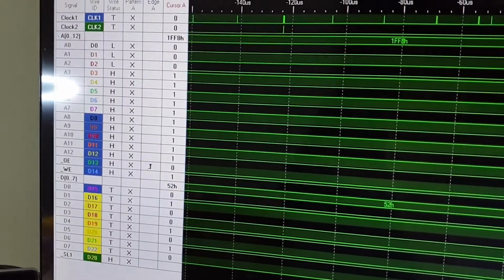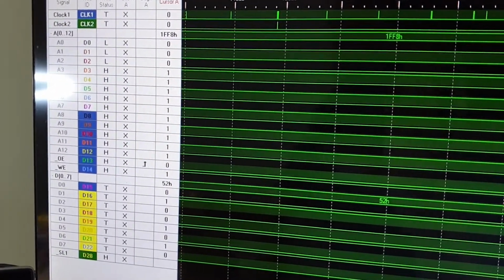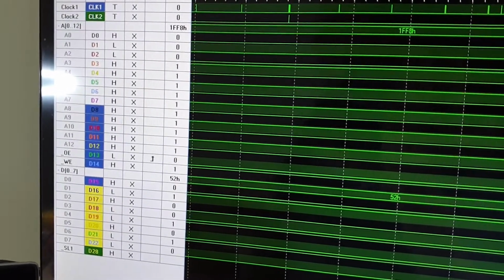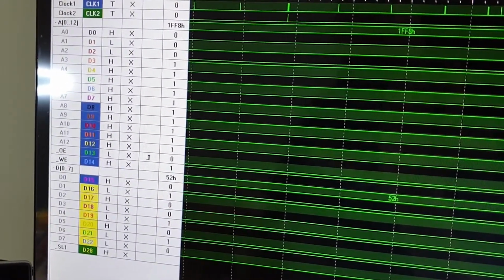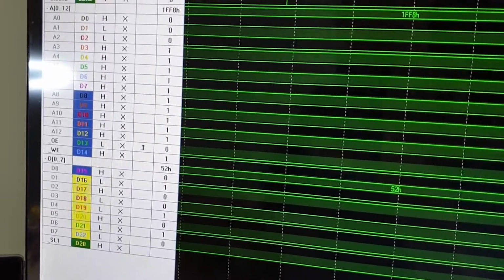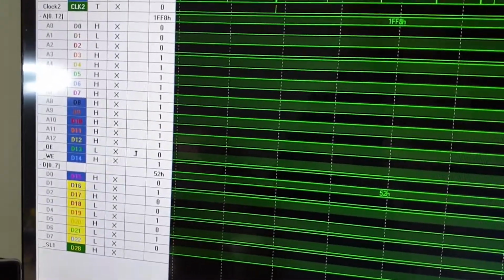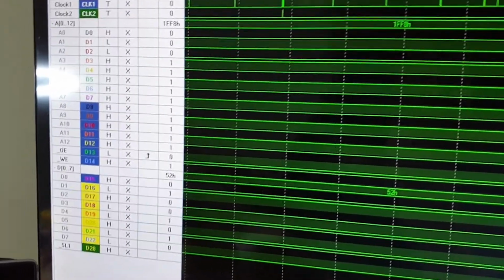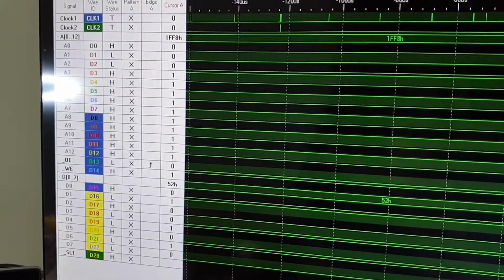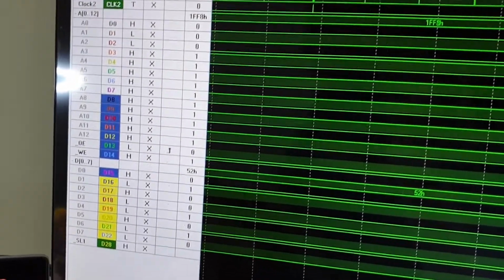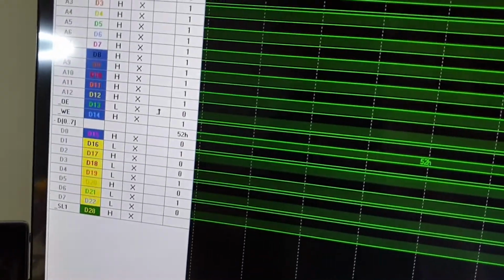And then if I go back and want to write it again, I can write another value like that. Write enable, no write enable, disable the extended memory again. And this time I'm reading high, low, low, high, which is 1FF9. Now, because I was writing to 1FF8, of course we're not going to see anything. So if I want to do that, I have to set the memory address to be 1FF9 on my external memory bus. Thus proving that I wasn't writing to the wrong memory address, which is a good test in itself.